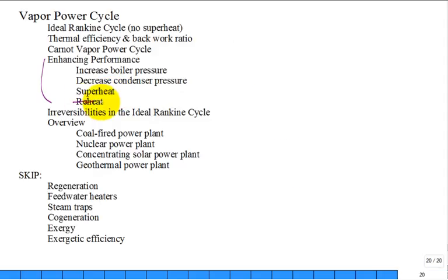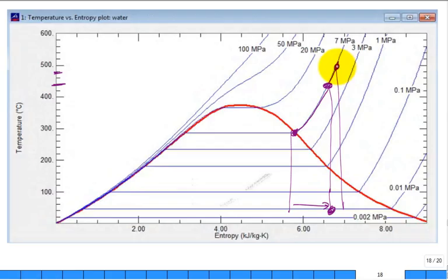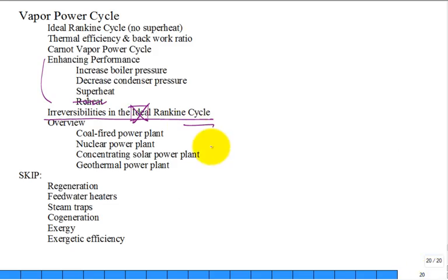I didn't cover reheat. We don't cover reheat. And if you have irreversibilities in the Rankine cycle, it's no longer ideal. What would it do to the turbine? It kicks it out. You have to do a two-step process when analyzing a turbine: first isentropic, and then using the isentropic efficiency of the turbine. Well, I didn't cover this, but maybe I'll touch on it next time.